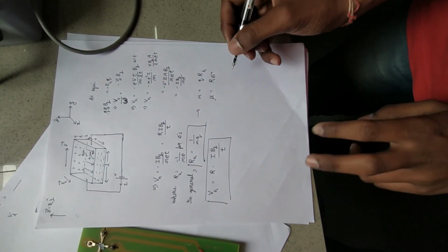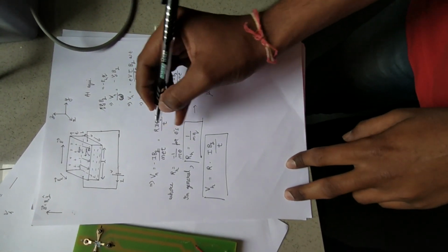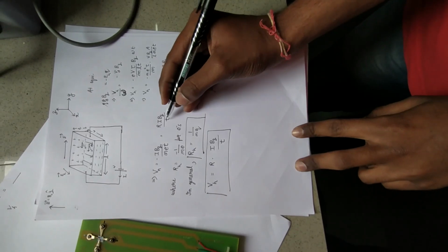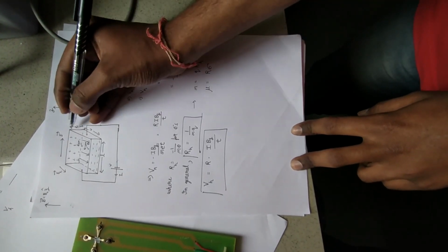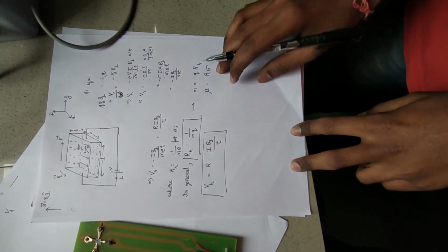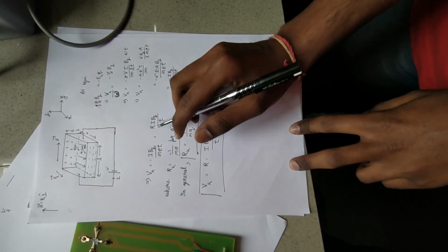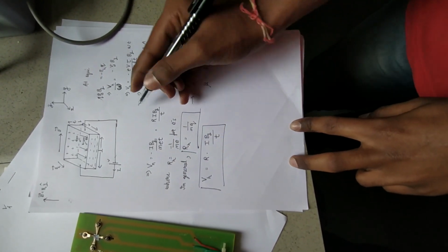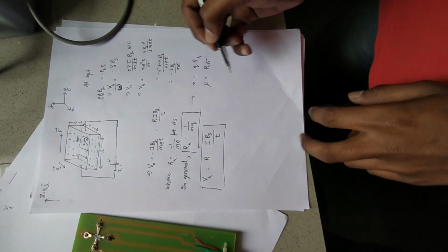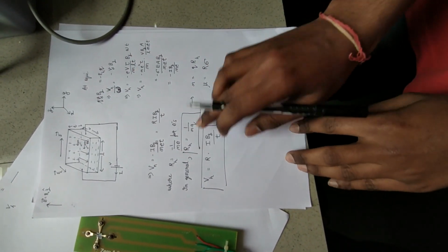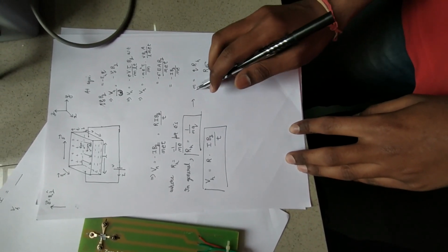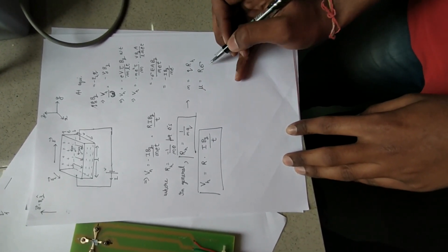The other proportionality factors include a constant which we call the Hall coefficient, and the thickness of this material. So by plotting the variation of Hall voltage with either current or magnetic field, we can obtain the value of the Hall coefficient. Using this Hall coefficient, we can do further analysis to determine the charge carrier density and mobility.